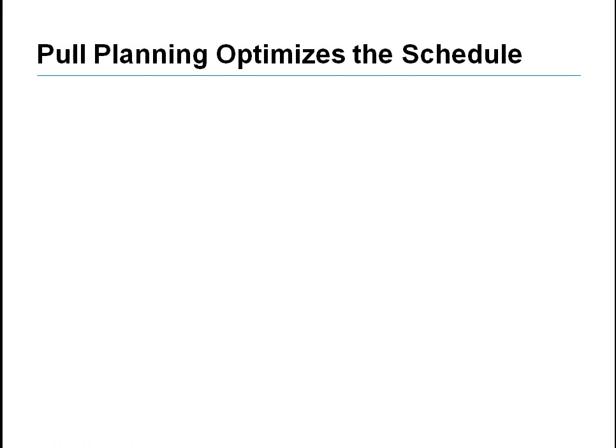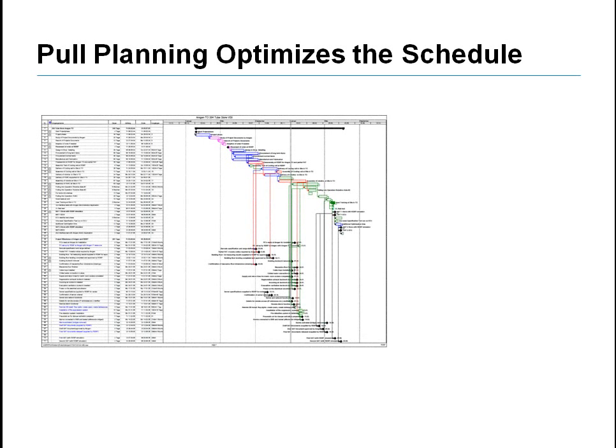Another method for increasing field productivity is through pull planning. Traditionally, work schedules are pushed out to the trades by the superintendent or master scheduler. However, in more cases than not, and for various reasons, the trades are unable to meet this schedule. In other cases, excessive float is built into the schedule as a contingency, which artificially pushes out the schedule longer than needed. In still worse cases, trade stacking is incurred when no allowances are built in.